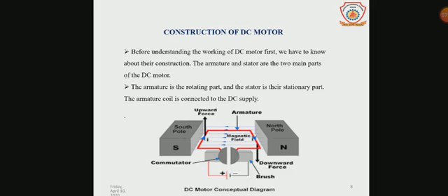An electrical motor consists of a rectangular coil of insulated copper wires which is mounted between the curved poles of a horseshoe type permanent magnet in such a way that it can rotate freely between the poles south and north, that is S and N. The device which reverses the direction of the current through a circuit is called the commutator.